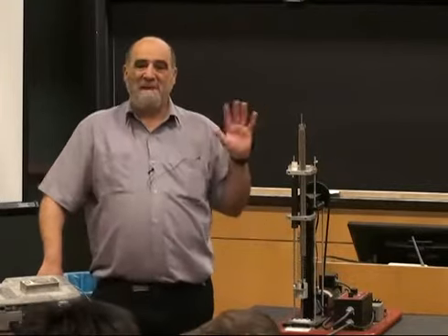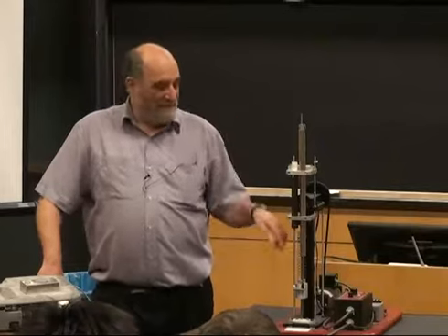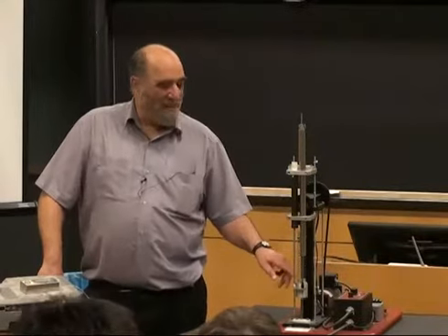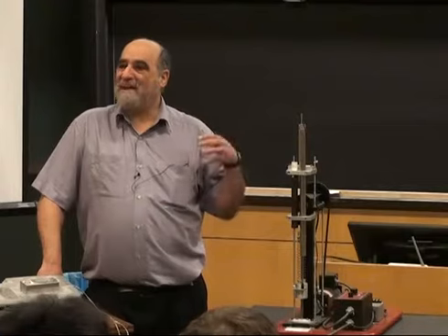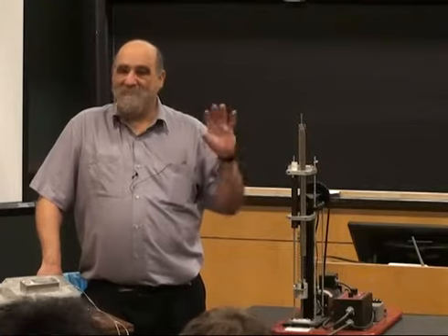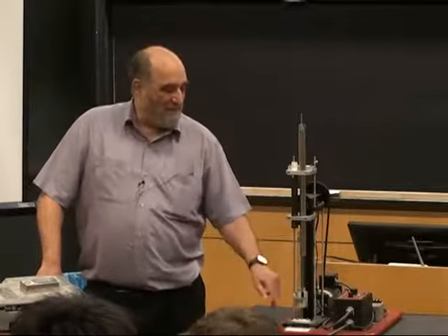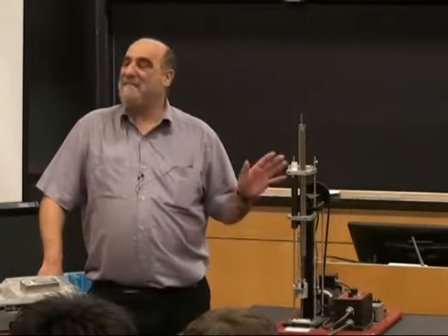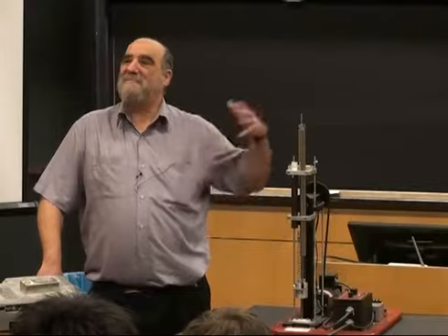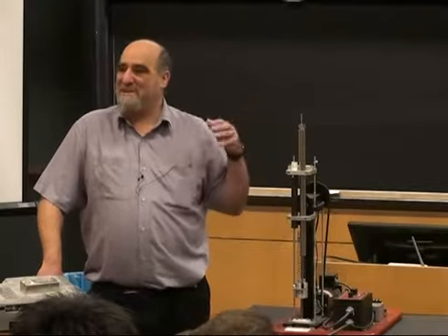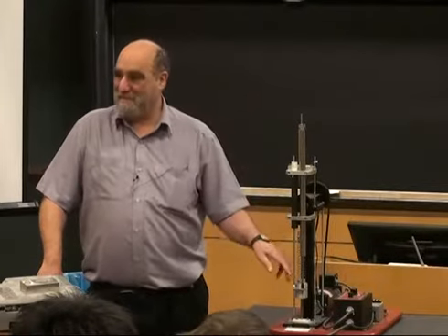Now what's one reason that maybe it doesn't matter that much? Lots of systems, ones which vibrate a lot, most of what's going on is with the spring and the mass. The friction is a relatively small term. It's big enough so that you get to some kind of steady state, but not so big that it really matters. So all you want is some term in there which throws away a little energy, and that catches most of how the system works.